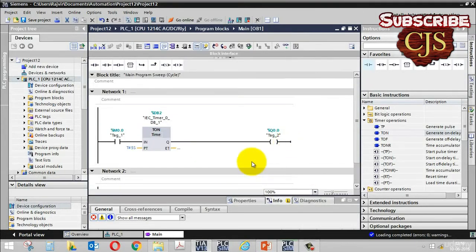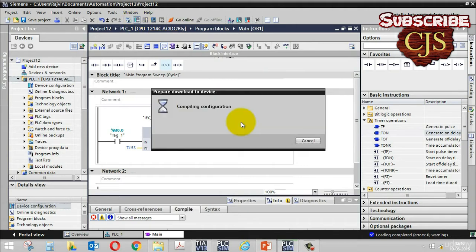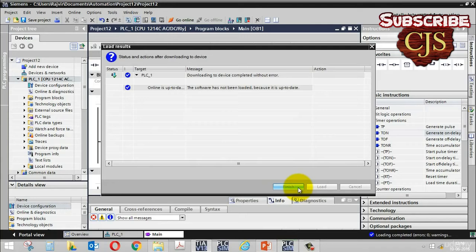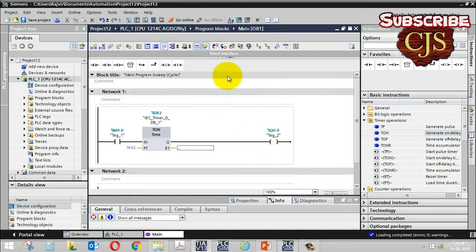So it will execute the task. Now the simulation has been done. So if you check your PLC SIM, that window must come here. Or if you notice, the next step is you have to download to device. So click on this one. So it will load the software and click finish. This is just to make sure your software is downloaded.